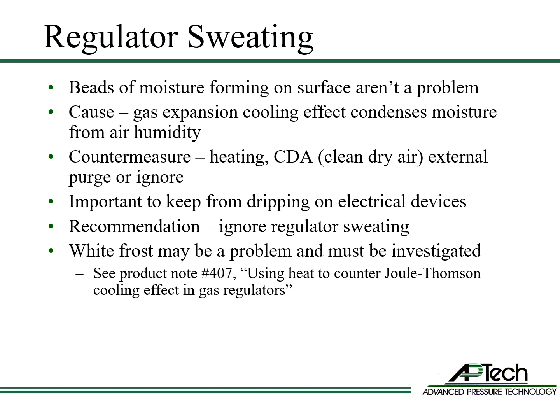The cause is the gas expansion cooling effect, condensing moisture on the regulator surface from humidity in the air. The countermeasure is heating, clean dry air external purge, or to ignore. It is important to not let water drip on electrical devices. Our recommendation is to ignore regulator sweating.